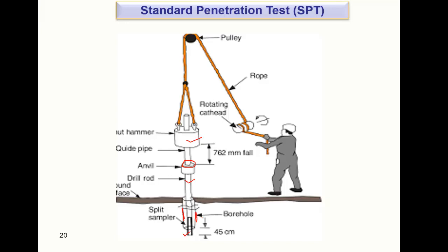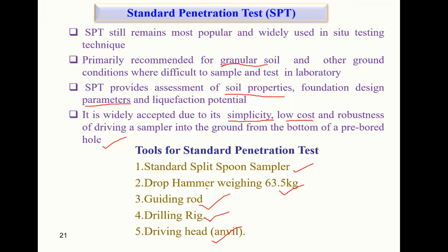Okay, whatever it is, just drill up to this, suppose. Maybe you make a borehole up to this, and after that you want to take a sample, and then you start with the SPT. Is that okay? Yes, sir.